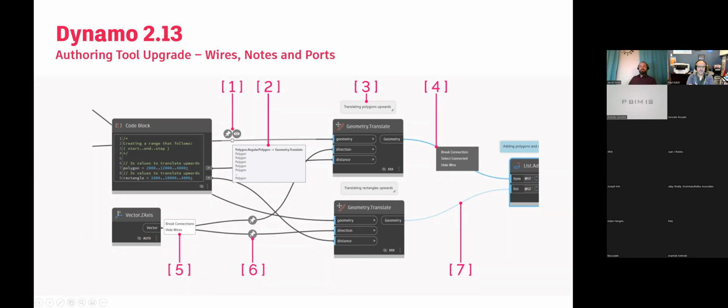The big reason for this, again, if you think of some of those really big graphs, like generative design graphs, you want all your inputs off to the left, and the action might be happening in the last node on canvas. So either you've got 7 sets of pins to move that wire along the base before you get it up where you want it, or maybe in an older version, you were using an object.identity to just pass the data in one side and out the other and route those wires. With this, you don't have to worry so much about that. You can just wire it up and then hide the clutter of the wire and know that it's coming from somewhere else, which is kind of nice.